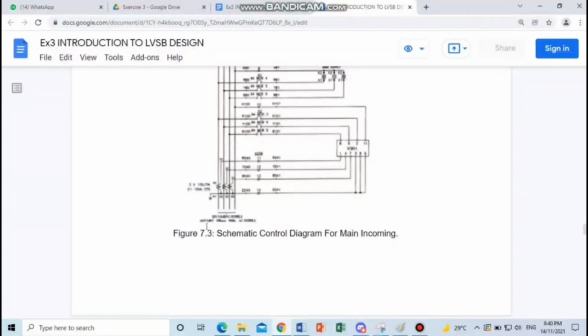So how do you know it is three phase? Here, this is the red cable because the label is R. This is the Y because the label is Y, and this is blue because the label is B, and the last one is E. It is neutral, and it connects to the ground. This cable will connect to the kilowatt hour meter.